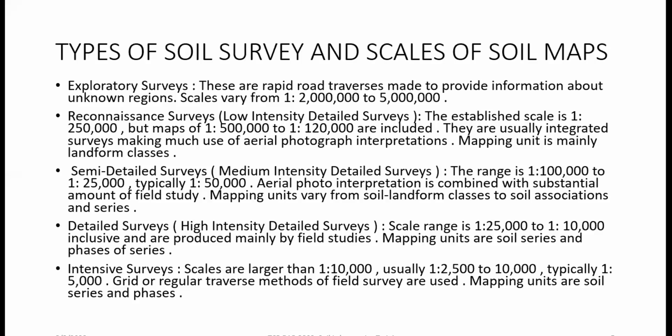In a semi-detailed soil survey, normally you take a soil sample at intervals from every 2 kilometers down to every 500 meters.